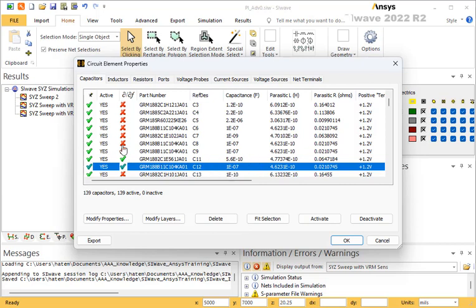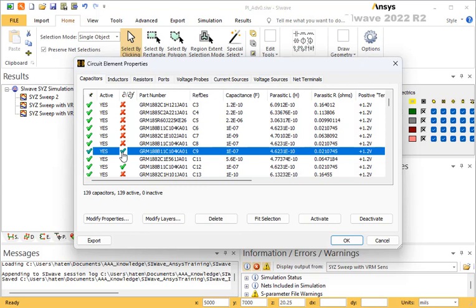And you come to this column and you just click on it and it will turn into a green sign, yes, okay? Or you click on it again and it will turn into a no, cross. So that's how you activate the sensitivity of this. Like you want SIwave to calculate the sensitivity of the S parameters or the Z parameters with respect to these numbers.